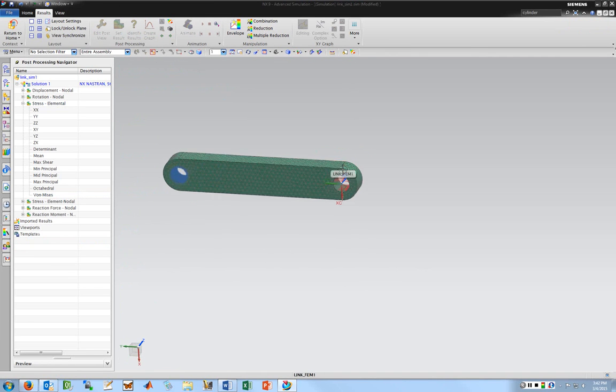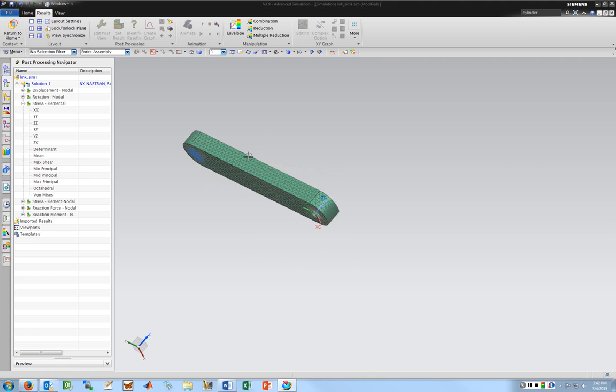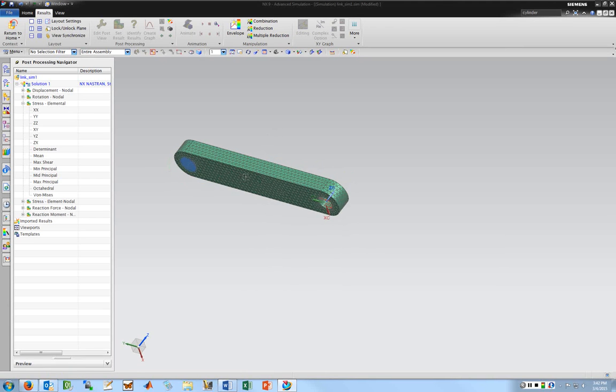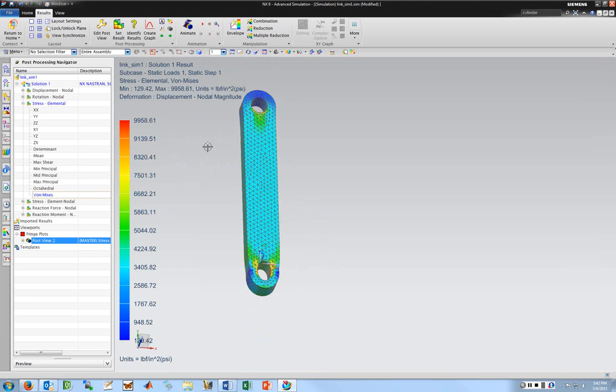Oh, I forgot, it's 2,000 pounds, so yeah, that makes sense. So it's a 1/2 inch cross section, 2,000 pounds, 1/2 inch. That should give me, divide 2,000 by a 1/2 inch, 1/2 square inch, I should say. That gives me the 4,000 pounds per square inch. So bring up von Mises. And so that's a pretty simple validation.